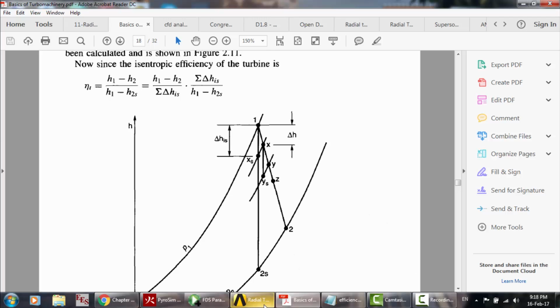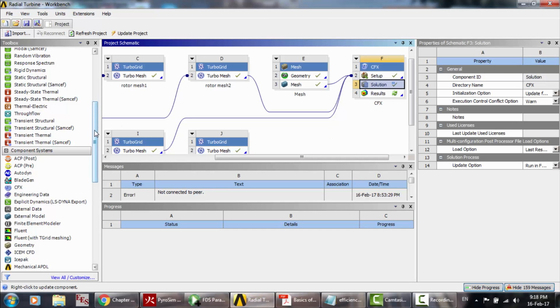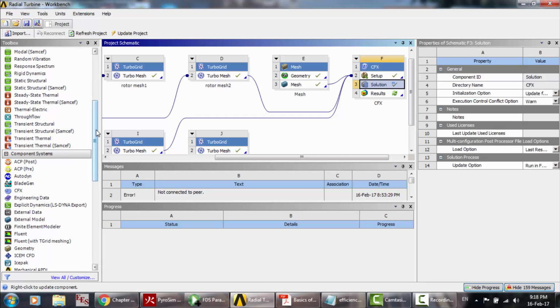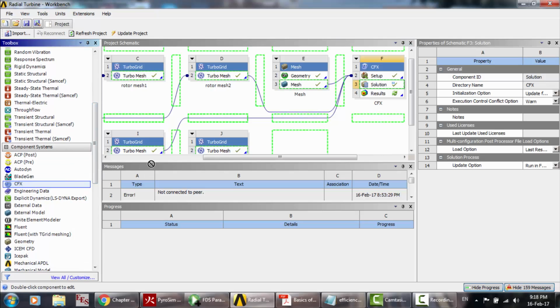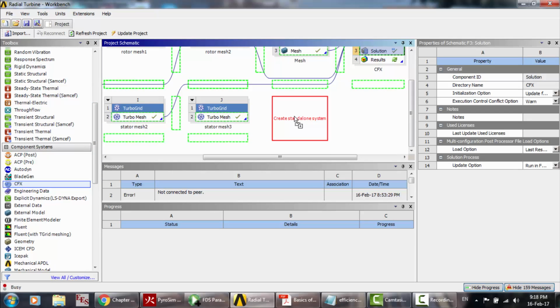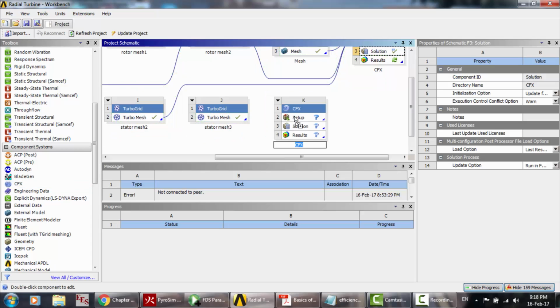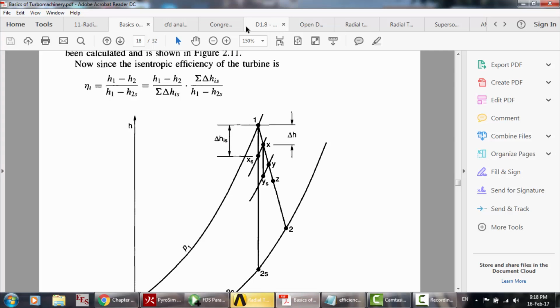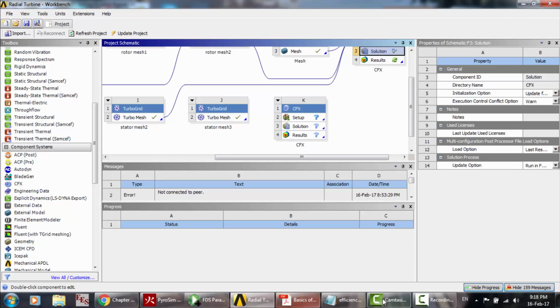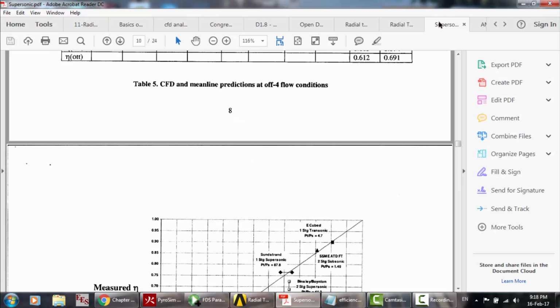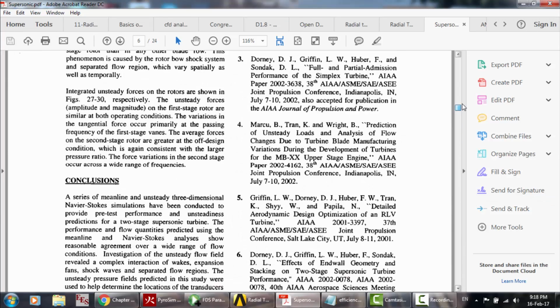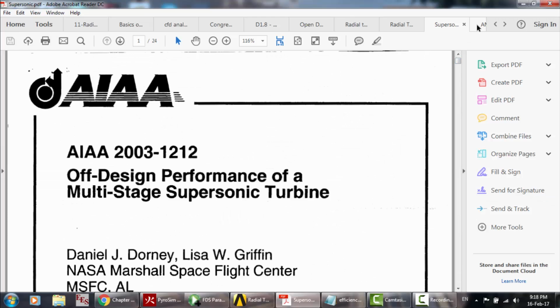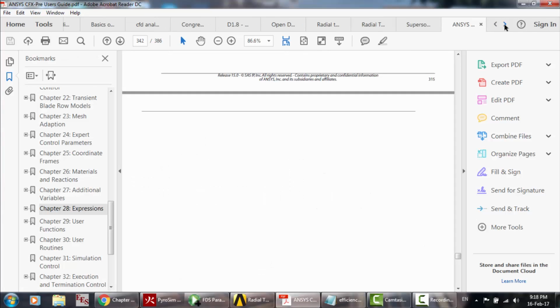So now let's start. We're gonna carry out the simulation without the volute at first, and then we're gonna complete the tutorial with the volute. Before you open CFX, you have to do the mesh dependence study. It's according to your model and the accuracy you need.